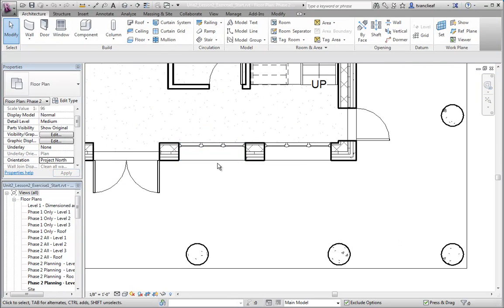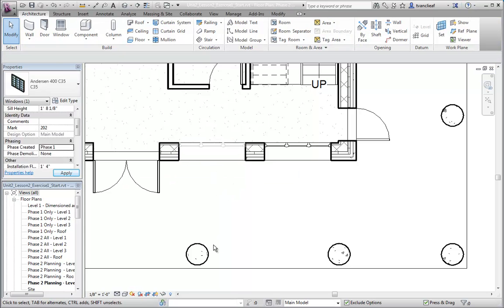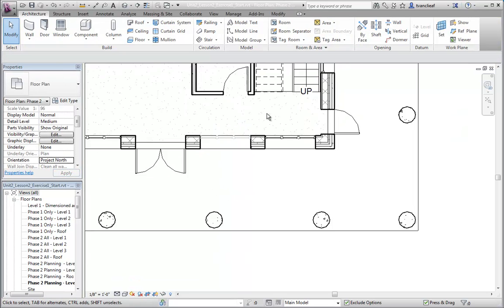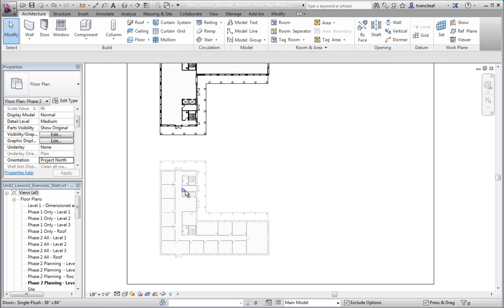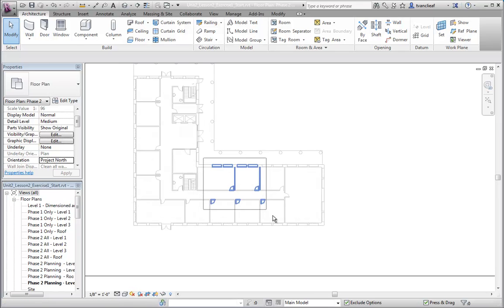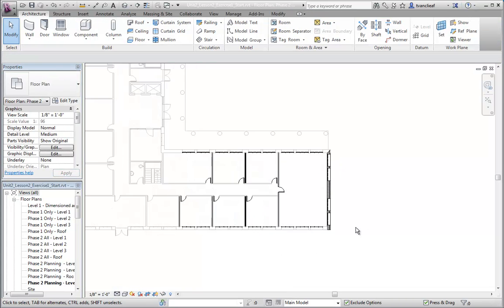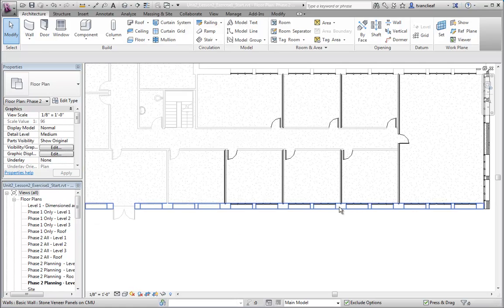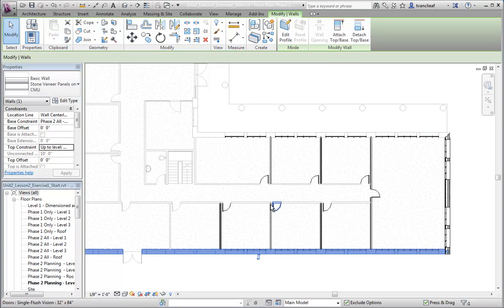So if you do define phases, you can just simply select them and change them, and you'll notice that this one now has become gray. So in this situation, they had one phase per building, but if they were, say, doing multiple parts of these buildings, you could select all these aspects and change these to phase 2, and now you'll see that these parts appear black, and those parts of the construction that were done before or after whichever phase are appearing in gray.